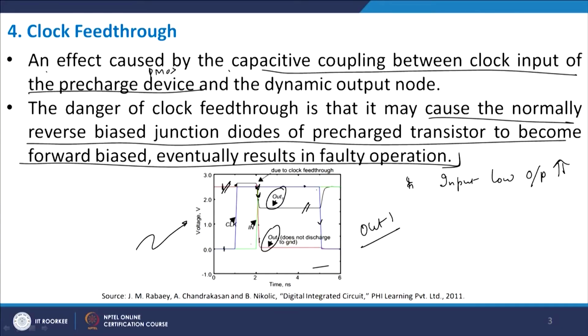So, it should ideally latch to a value equal to VDD, it does not; it falls to a value equal to out 1. So, even under the criteria that your A and B are both equal to 1 and you are designing an AND gate, the output voltage will not go down to 0, but slightly above 0, as I discussed with you now. This is the first scenario or observation.